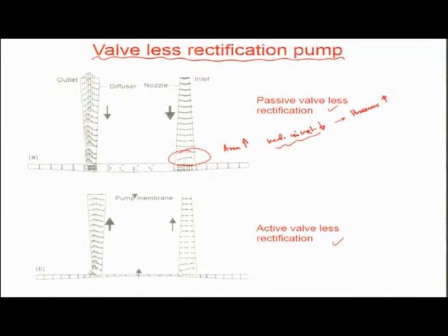So there is a pressure rise, and this is a high pressure region which is developed because the flow gets slowed down here. The velocity falls here, so the velocity head is converted into the pressure head. On the other side, I have a diffuser arrangement where there is a lower cross sectional area which eventually changes into a higher cross sectional area, but because of this lower value of area, the velocity head is more.